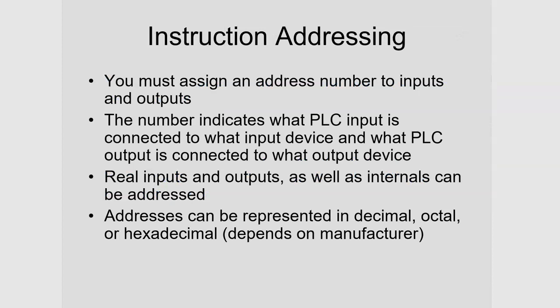I'm not going to say too much about addressing. We've been kind of saying a little bit about it in several other slides. So you know there's got to be a way for you to map the actual screw terminal, the instruction that you write, and the bit position in the output image table or the input image table. There's got to be a way to map the three together, and you do that through addressing.